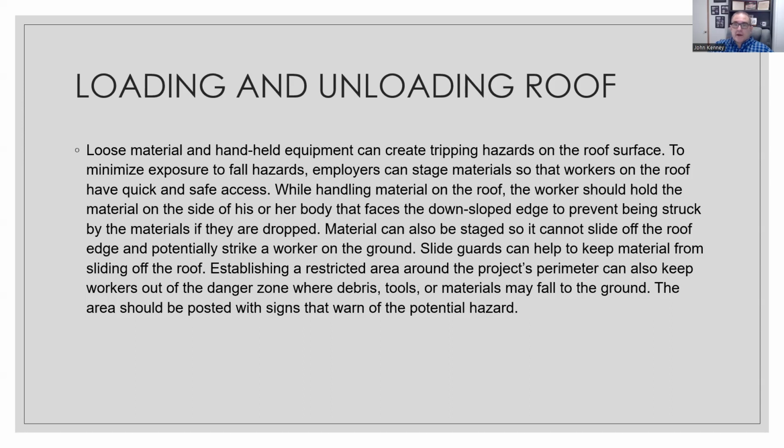Establishing a restricted area around the project's perimeter can also keep workers out of the danger zone when debris, tools, and material may fall to the ground. This area should be posted with signs and warnings. So sometimes, especially if you have the public near your sites, you need to have a danger zone around your projects where somebody cannot get into your work area perimeter. So again, all these things, you want to have these plans in place. This should be your initial safety plan, so this all falls naturally to you when you hit your job sites.